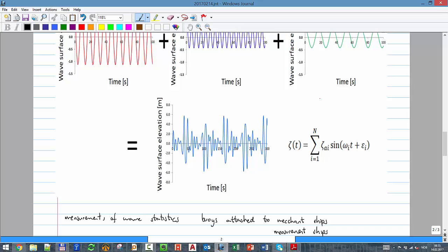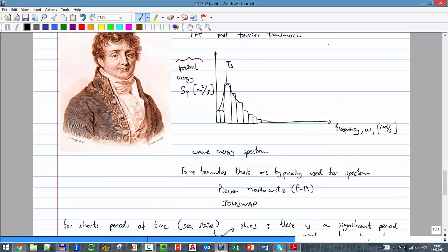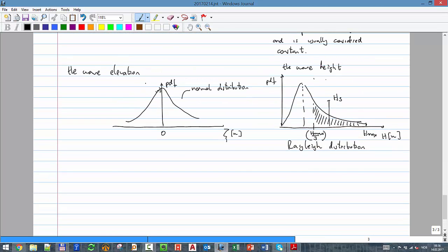So we said all the variations in elevation follow this Gaussian distribution, and all the variations of height follow this Rayleigh distribution. Now I calculate a number from this distribution that represents this particular state, and that number is this Hs that I told you. So don't be confused about how we calculate it. We just want to get two numbers, frequency and height. That's what we call significant wave height.